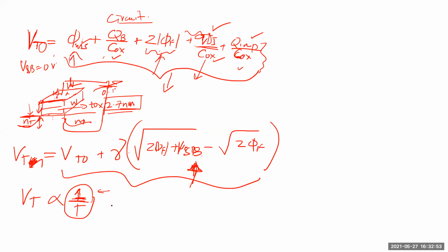So for example, going from -40 to 125, which is the industrial range. Let's say you're designing for an automotive or industrial application, then you have to meet all the specs from -40 degrees C to 125. And a typical VT will vary. For example, if you have 0.4 volts or 0.6 volts nominally at 27 degrees centigrade, from -40 to 120, it can vary all the way from 0.4 to like 0.8, depending on the process.